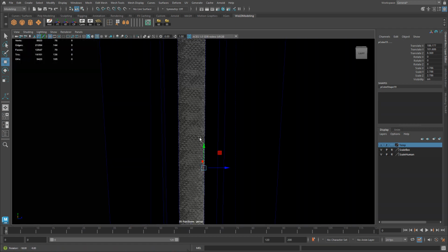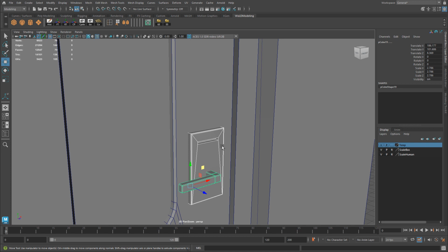Now, because I wanna have them on both sides, before you duplicate, you have to UV your objects, and it's a lot faster if you UV these now, and then you can duplicate them for the other side, so you can overlap those UVs on top of each other so they use the exact same texture. That way it'll save you time, so you don't have to UV exact same geometry twice. But since this is only modeling, this is only Let's Model episode, I'm going to UV this outside on my own. Let's go ahead and have it on both sides so we can see it in engine modeled as well as in Maya.